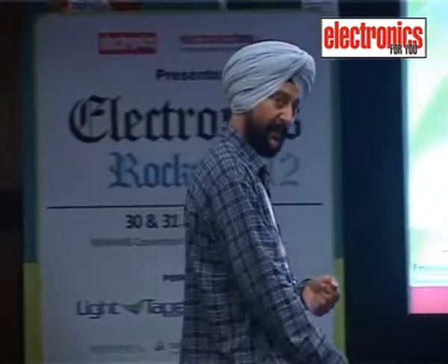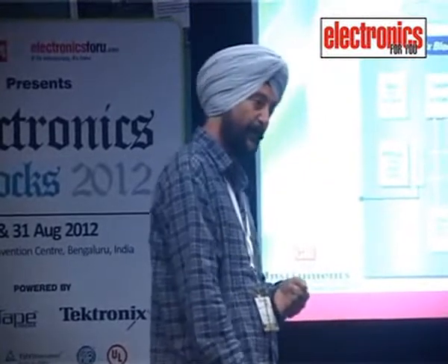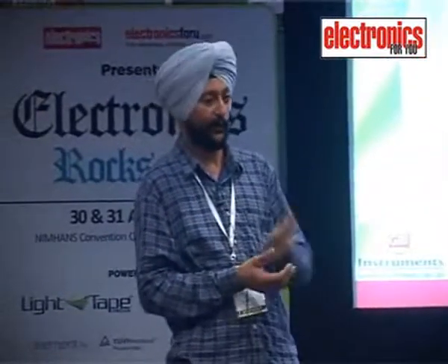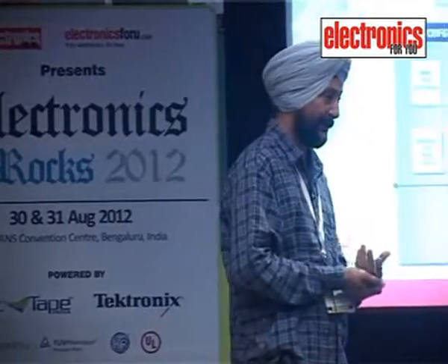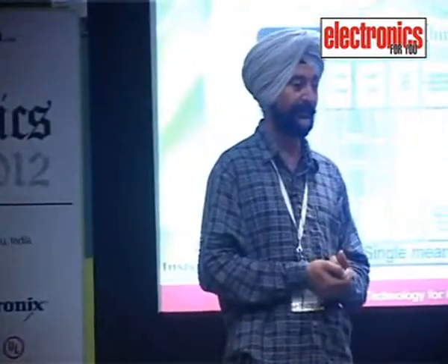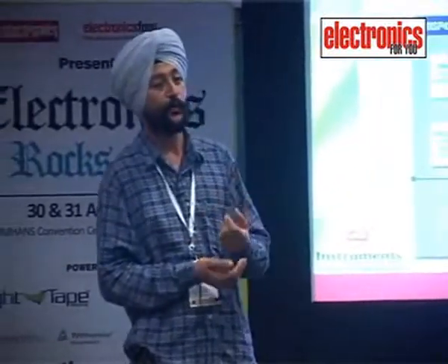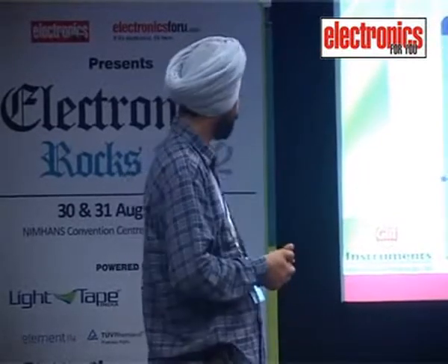It works like this. But when you suddenly add something to the program counter, it jumps to a particular location. So without using a jump instruction, it will jump to the particular location, right? So when you are implementing an RTOS on this kind of chipset, the MSP 430, you will be able to do more things in less time and in less memory space, right?